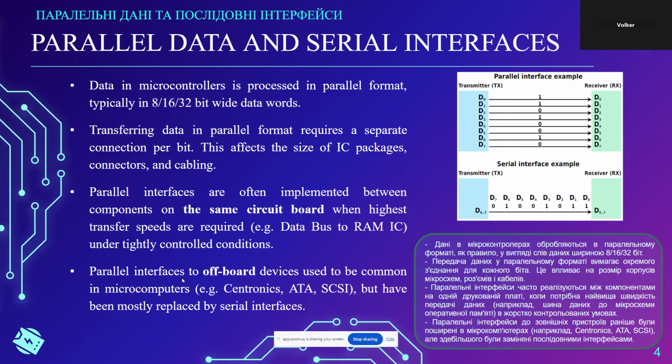Parallel interfaces to off-board devices used to be common in microcomputers, Centronics, ATA, SCSI, but have been mostly replaced by serial interfaces. People who have been building PCs for the last 20 years probably are aware of the old style ATA interface that used a 40-pin ribbon cable.